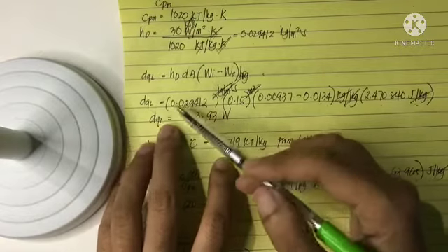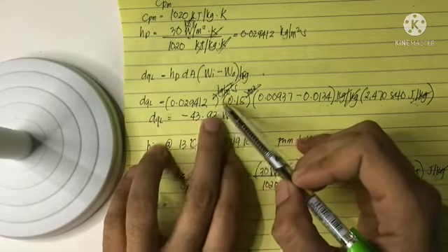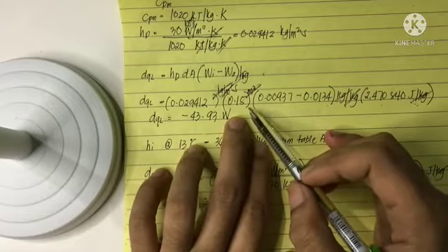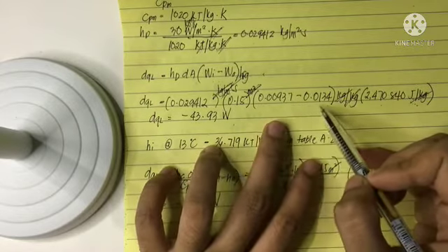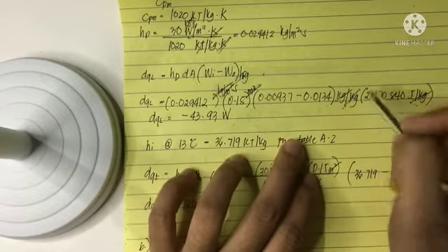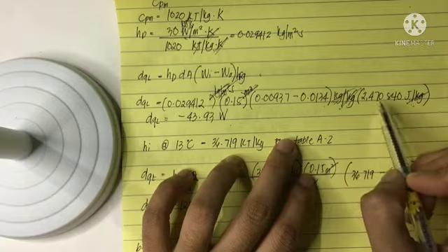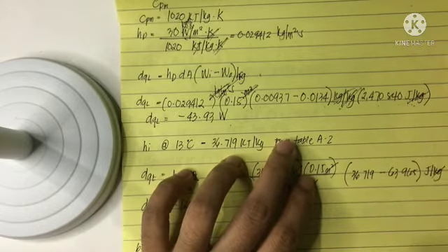By solving, the rate of latent heat is equal to 0.029412 kilogram per meter squared second times 0.15 meter squared times 0.00937 minus 0.0134 kilogram per kilogram, so that cancels out, times 2,470,840 joules per kilogram,